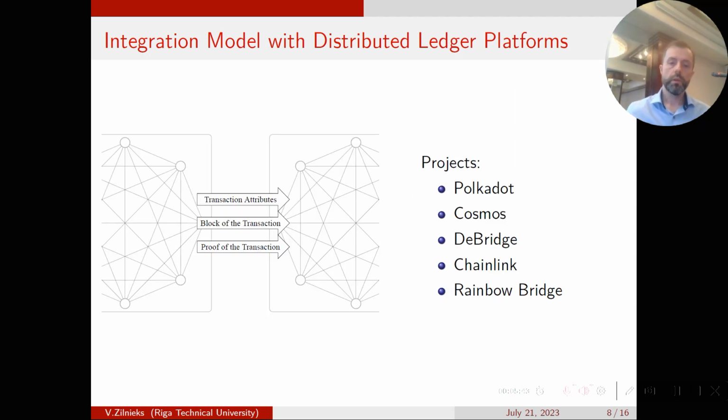So in this way, the code returns the temperature of the indoor environment and the temperature profile in the wall, and so we can calculate the ventilation load and the transmission load. We can calculate, at full load, the power of the electric heat pump. We can also calculate the COP, the coefficient of performance of this machine, this electric heat pump, suggested by a correction by the rule UNI EN 14825. We can calculate the capacity ratio, that is a factor of the machine, and so we can calculate the correct COP, that is a function of inner temperature, outer temperature, and this factor.